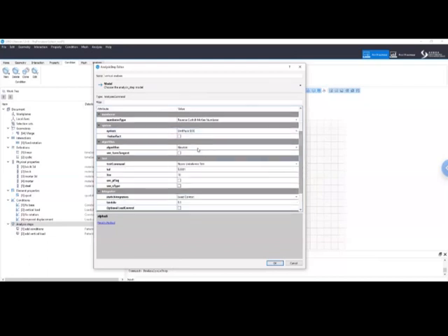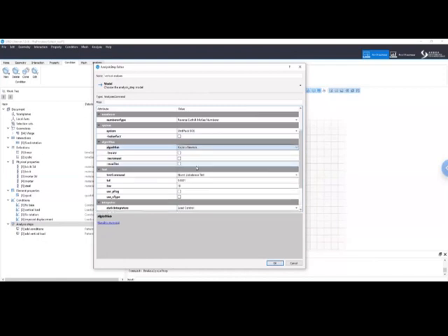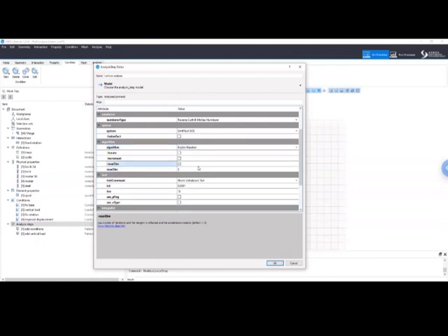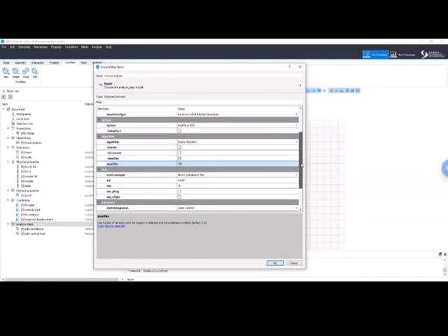Now, in this case, we're going to use, instead of the Newton method, the Krylov Newton, just because we want to make it a little bit faster. So we tell the Krylov Newton to update the tangent matrix every, let's say, 100 iterations, just to make this one use the tangent matrix only at the beginning of every step.